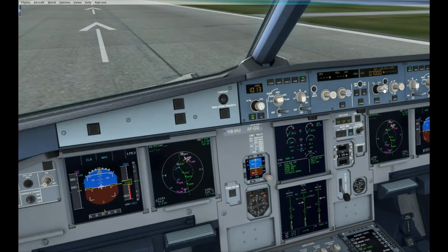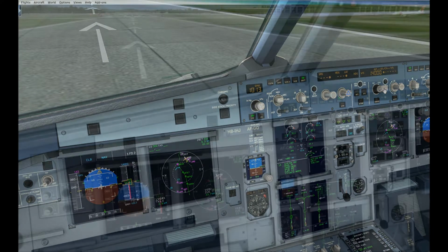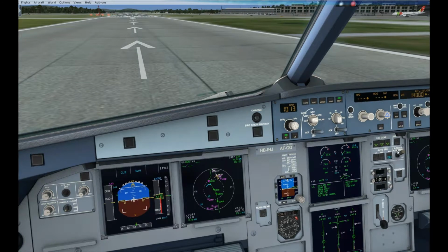I'm now going to set my cruise altitude to 14,000 feet, and I will set that as a single altitude so that we will make a steady climb to our cruise altitude without any steps in the altitude climb. I have now checked that I have fuel for the flight, and I'm going to set flaps 2 for takeoff. Flaps 2 now set. We're now ready for our takeoff roll and our climb to 14,000 feet.